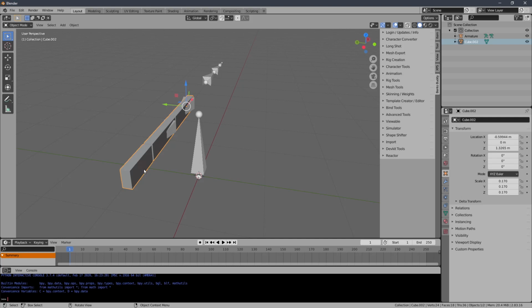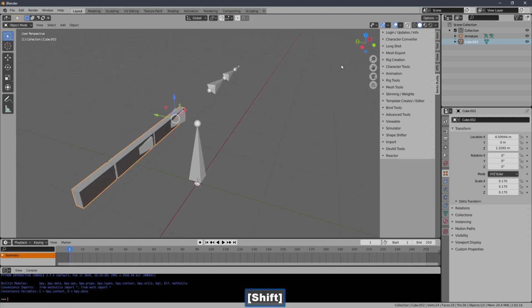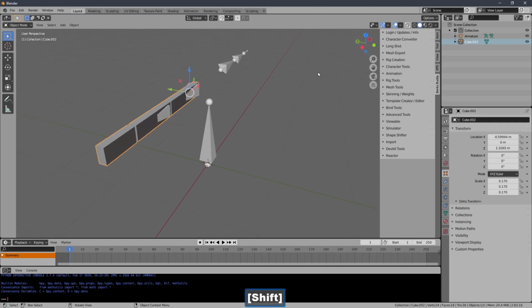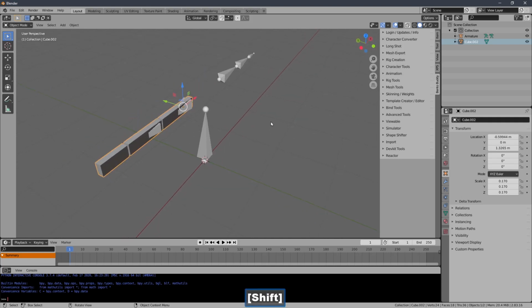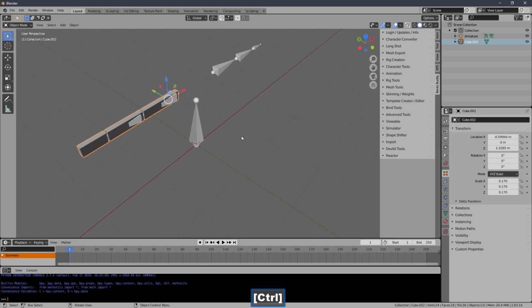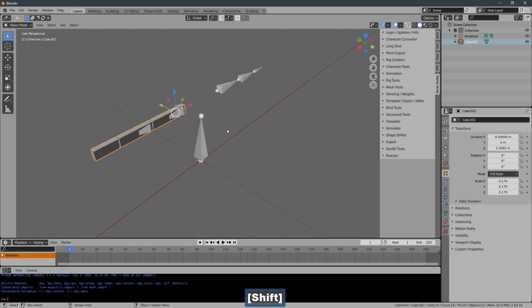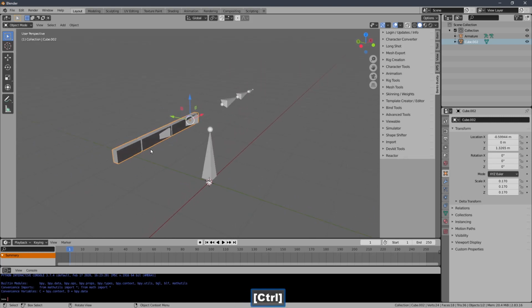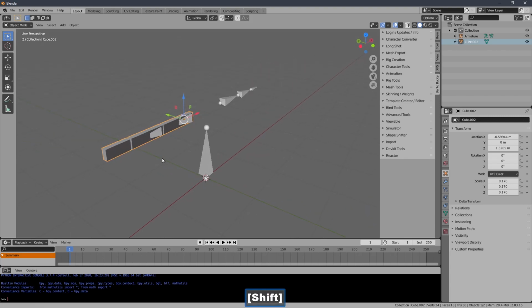So this is the palm forward, and it's going towards the negative X direction, negative Y direction right here. You can tell that this is the negative because it doesn't have a pole on it. The positive has the pole on it that connects to the Y, you see. Anyway, so this is the normal angle or orientation of a rig when you make characters in Blender, except we would usually like the arm, the palm, facing down. That's not always correct. Once in a while we do have the palms facing forward, but for Second Life it's always going to be down if you're going to utilize the in-world animations.